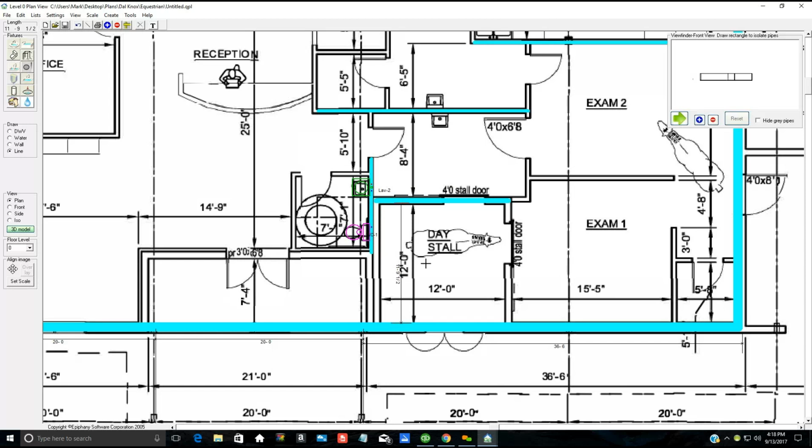And there's my dimension, 11 foot 10 3/4. And it's supposed to be 12 foot. So all I do is click on the wall, and I can use the arrow keys on my keyboard. And I'm just going to use those keys and move it up until this dimension here reads 12 foot 0. Gotcha. And then we'll do the same again.